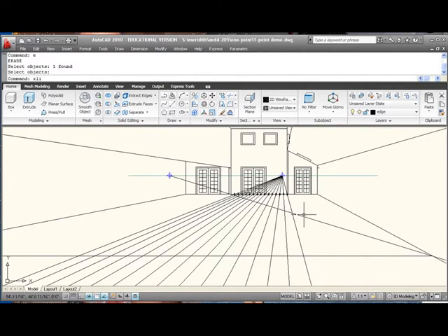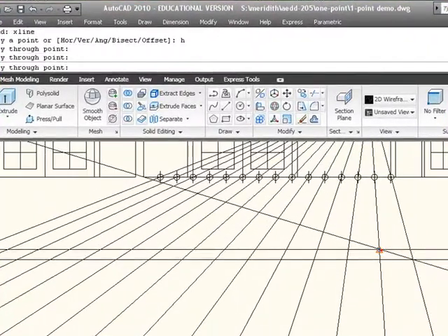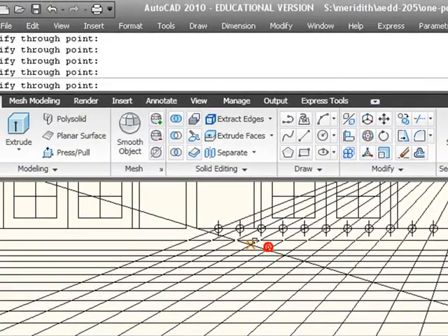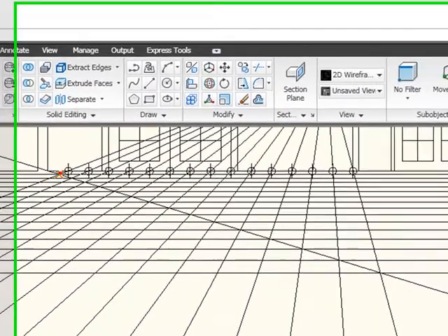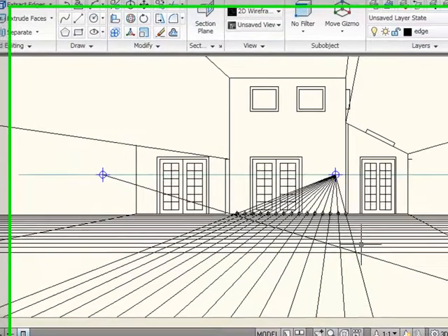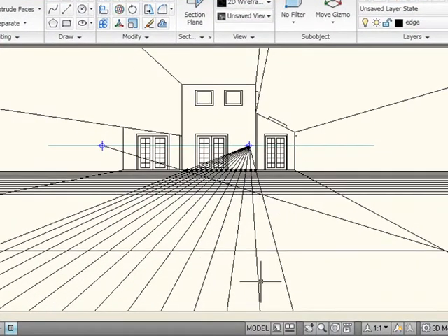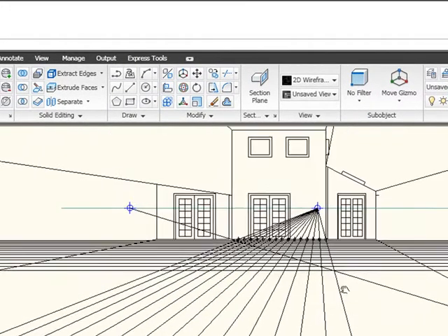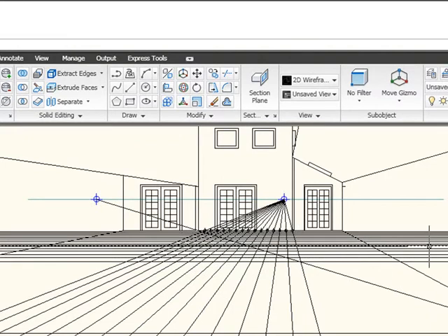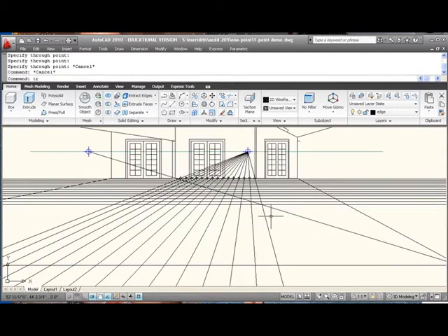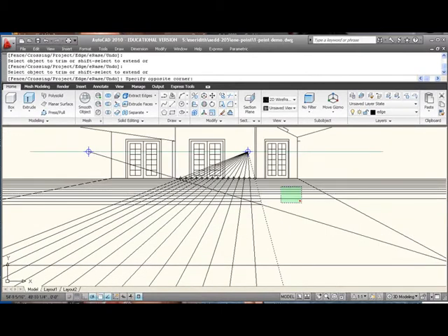And if we use the X line command, horizontal, I'll explain where we are feet-wise back here and why we don't have any more in between the 30-foot mark and where we're at back here. We only have 15 feet showing here, so we're only going to have 15 horizontal lines coming towards us. We have another 15 feet here that we don't have accounted for because we don't have another 15 lines going in either direction to lay those out. So if we put another 15 lines going in this direction, then we'd have enough information for us to get all the way out to here. So let's trim these lines back.